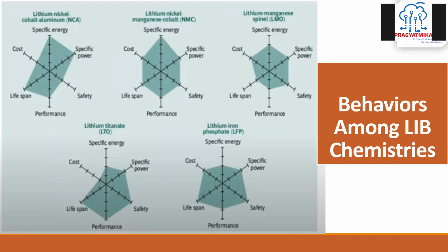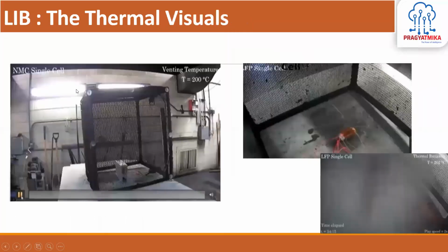It is completely dependent upon your application. What is your requirement? You need to select the chemistry, and the safety that you will have to ensure. Every chemistry can be safe, and every chemistry can be unstable. That's the same thing: if you do not have a good design of your pack, the thermal design, the electrical design and the mechanical design, these three being the basic things, then even an LFP pack can be a disaster for you. But if you have good design aspects, you can go well with the NCA chemistry also. Like Tesla is using NCA chemistry, and it is a good chemistry they are using.